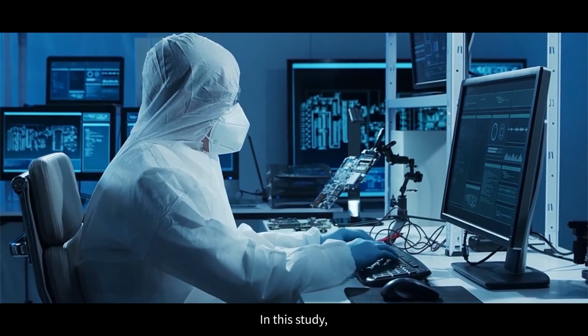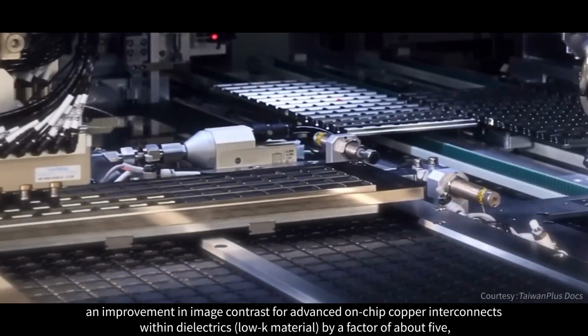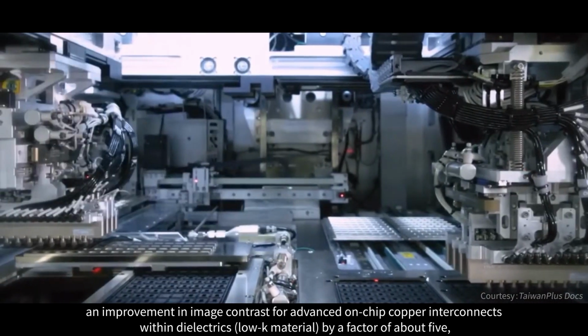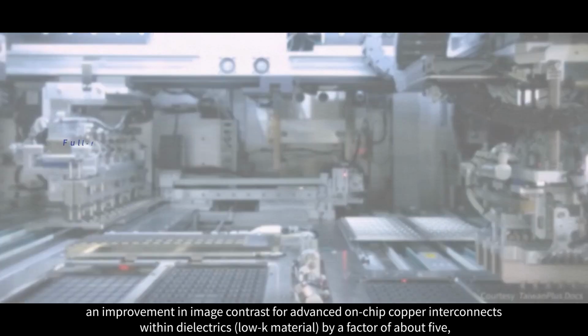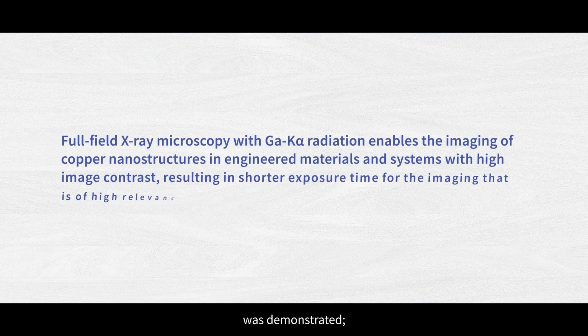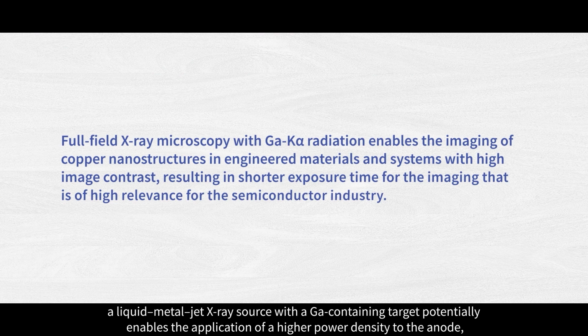Conclusions and outlook. In this study, the following occurred: an improvement in image contrast for advanced on-chip copper interconnects within dielectrics by a factor of about 5, compared to state-of-the-art X-ray microscopy imaging, was demonstrated. A liquid metal jet X-ray source with a gallium-containing target potentially enables the application of a higher power density to